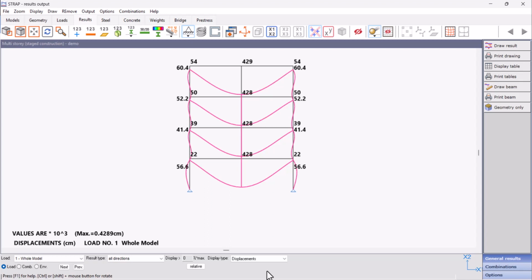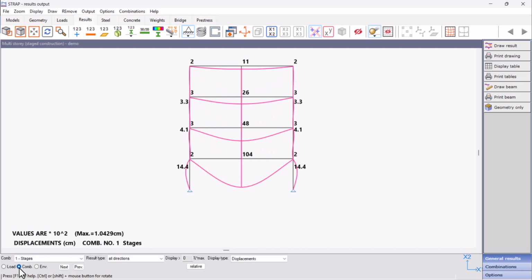When comparing the deflections between the load cases, the structure subject to global loading shows nearly identical deflections between the levels, similar to what is seen in the bending moment diagrams. The displacements of the nodes occur based on their initial positions before the loads were applied. In contrast, the structure subject to staged loading presents increasingly smaller deflections as the levels progress. But unlike the structure subject to global loading, the deflections occur based on the previous stage, meaning based on the levels below.